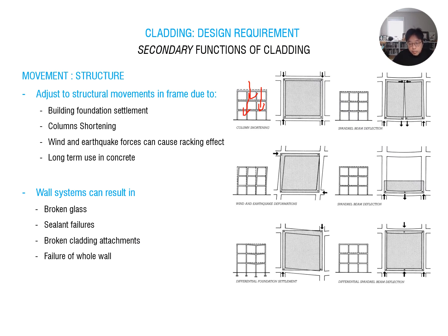Therefore, we have to provide proper column thickness and size based on the building height and weight. And of course, you have to think about lateral forces like earthquake or wind forces. In this case, you have to provide certain expansion joints and a certain gap between the window frame and the cladding design, or between the window frame and wall assembly, to provide some tolerance space to protect against this movement.